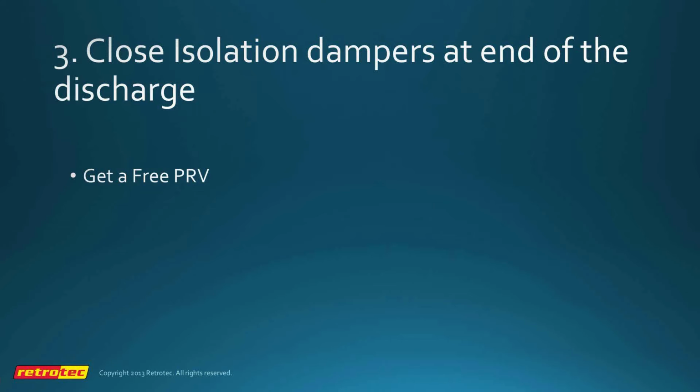So what I've done in numerous situations is I've advised them to consider changing the isolation damper sequence that is often part of the HVAC system. Typically we close all the dampers, isolate the HVAC, and then discharge. What I suggested is, let's not do that. Let's close the dampers towards the middle or the end of the discharge, so that we're actually using the leakage of the HVAC ductwork in order to vent pressure.